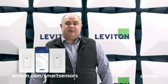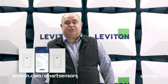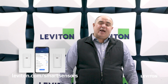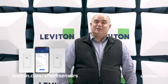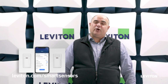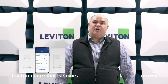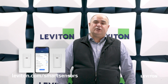particular device. But then we also have a 0 to 10 volt version of this that has phase cut dimming. What does that mean? Well, in some applications we've become aware that they are still using not just 0 to 10 volt, but also they are using two-wire dimming, which is often referred to as phase cut or forward phase dimming. And so we have developed a commercial solution for that using our multi-tech version platform.